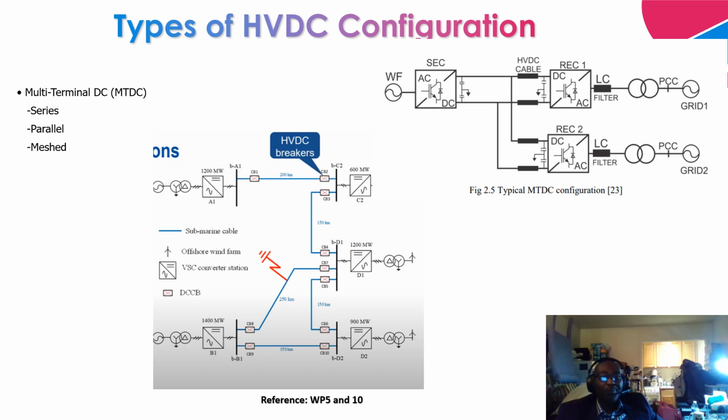So you have a step-up transformer that steps the wind farm voltage from the AC collection voltage, let's say from 33 kV to a 230 kV transmission level. So you have 1, 2, 3. These three converters are basically sending end converters. These are all located at an onshore substation. So the goal of these converters is to convert the AC voltage to an equivalent DC voltage before it is integrated to this DC transmission network with a DC bus and DC breakers.